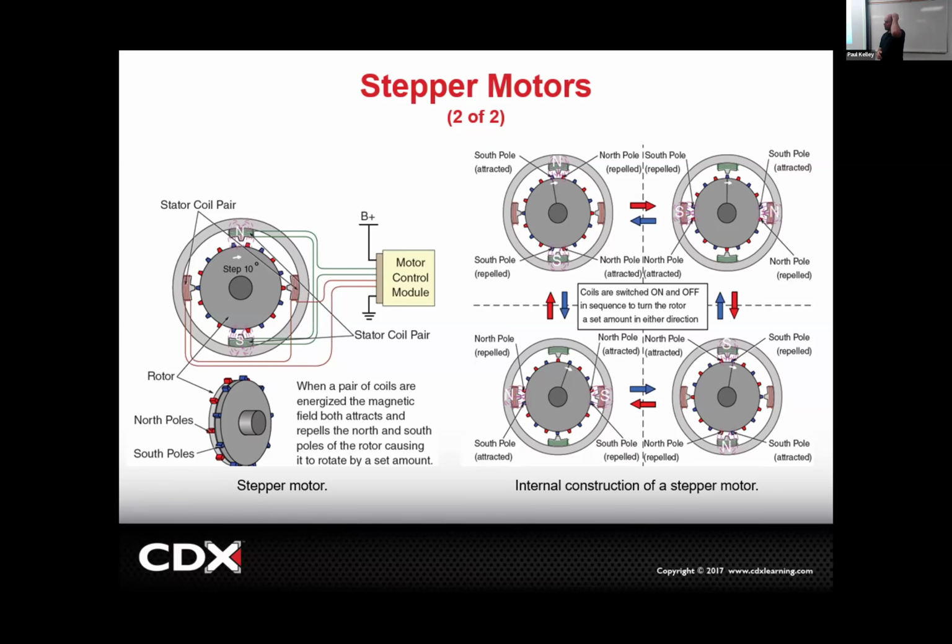Or like recently I had one where the oil pressure needle was buried past high. And it's like, that's not actually, the oil pressure is not off the charts. It spun around and jammed up against the other gauge. So you can actually go in with the scan tool and control these stepper motors and get them to sweep.